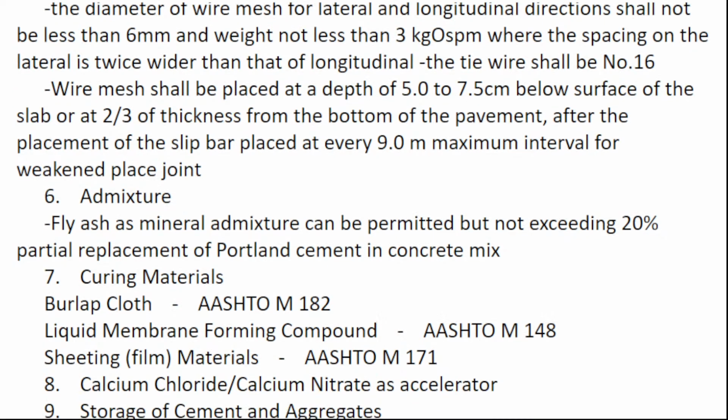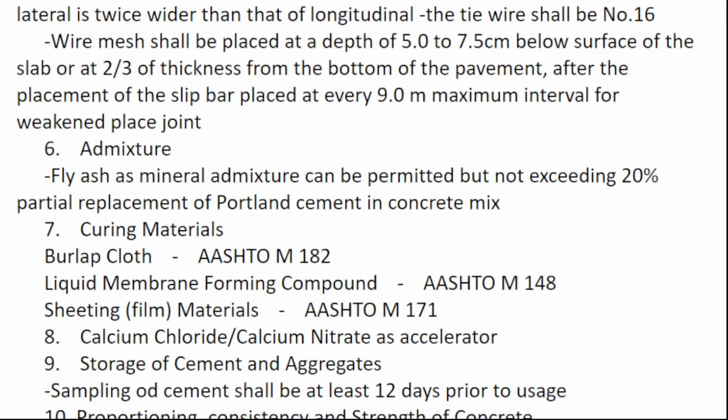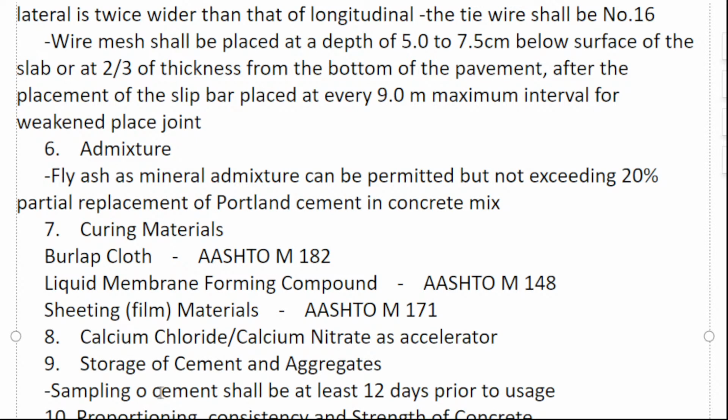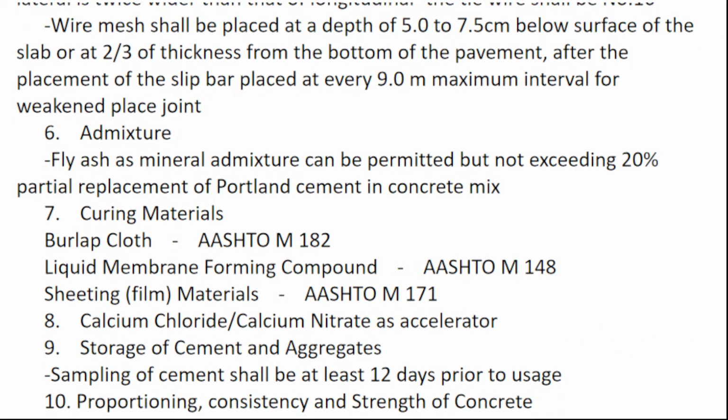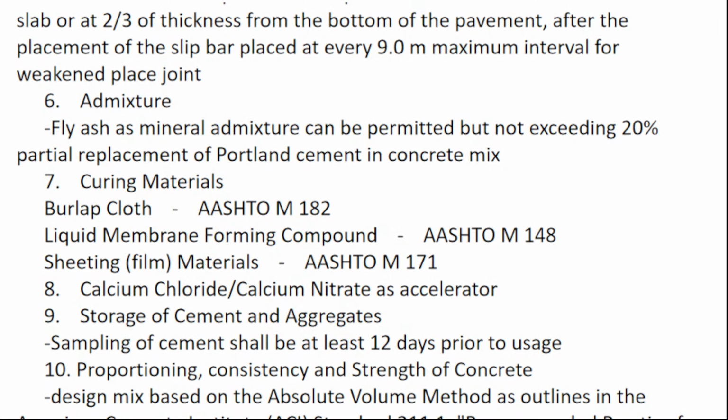And next, number 8, calcium chloride or calcium nitrate as curing accelerator. Storage of cement and aggregates. We need sampling of cement to be at least 12 days prior to usage. So, this is again a typo error. Okay, sampling of cement. Proportioning, consistency, and strength of concrete.